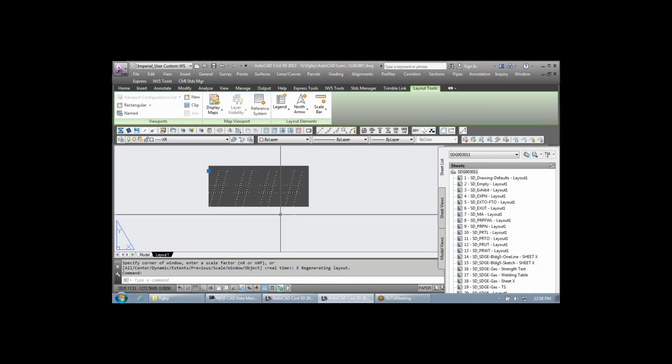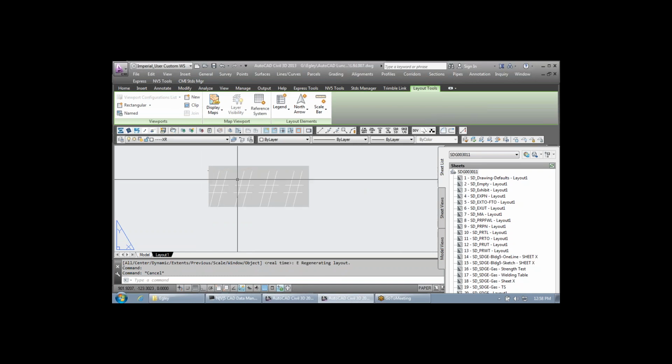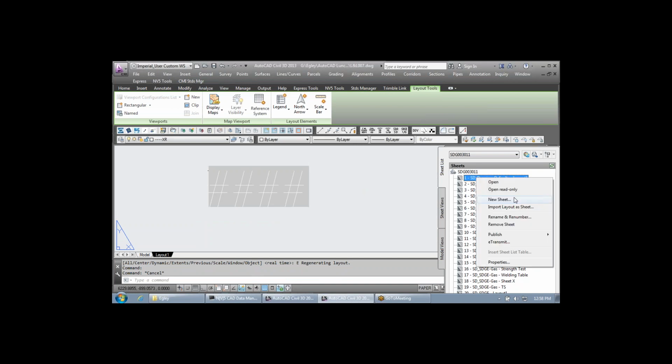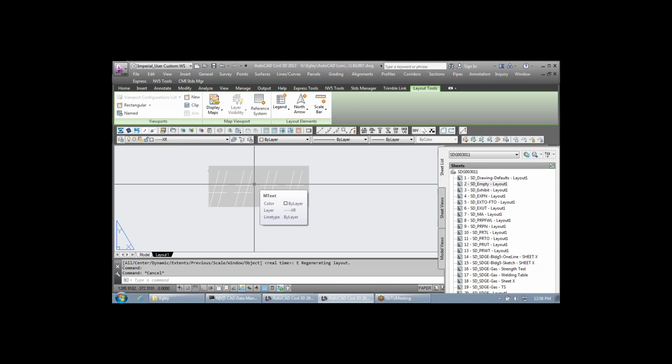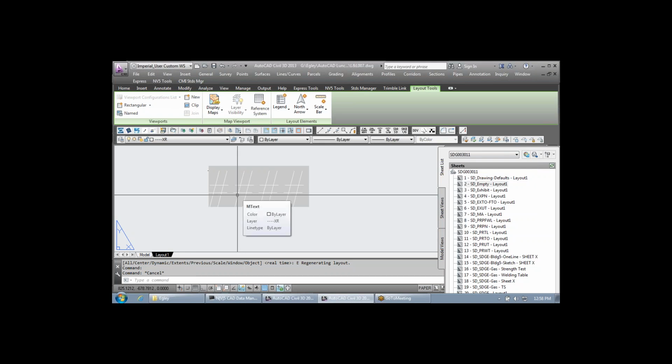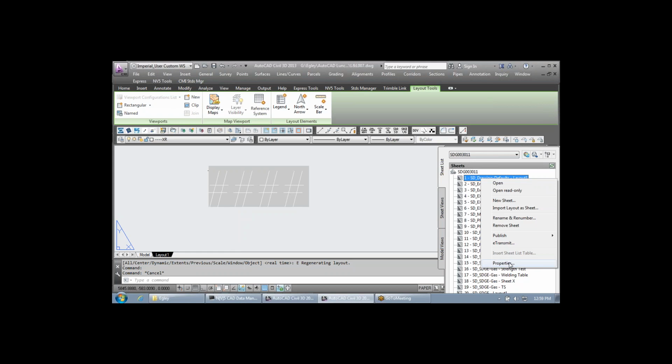So there's your field, and this is going to update and take whatever sheet is being identified in your sheet set. So then if I save this and reopen it, it would populate, and it would change based on however I manipulate my sheet set. So now instead of manipulating this piece of text in however many files and layout tabs that you have, well, 150 layout tabs, you know how slow it is switching from layout tab to layout tab. That's the last thing you want to spend your afternoon doing, right? Instead, now using that field, we can just edit it using our sheet set.